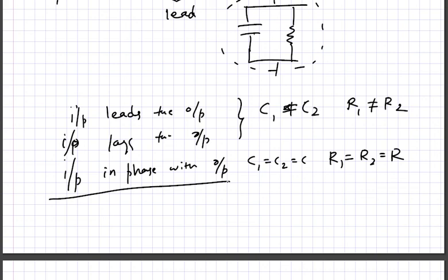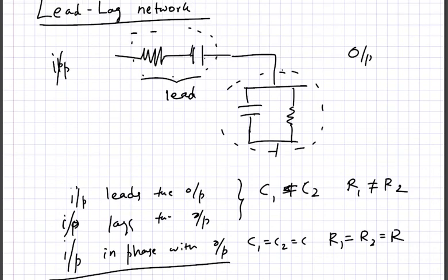Shunt capacitor means the capacitor connected to the ground, and the frequency which is allowed by the capacitor in series. So frequency selection is also done by this feedback circuit, another important job. At very low frequencies, the phase angle is positive and the circuit acts as a lead network. At high frequencies, the phase angle is negative and it acts as a lag network.